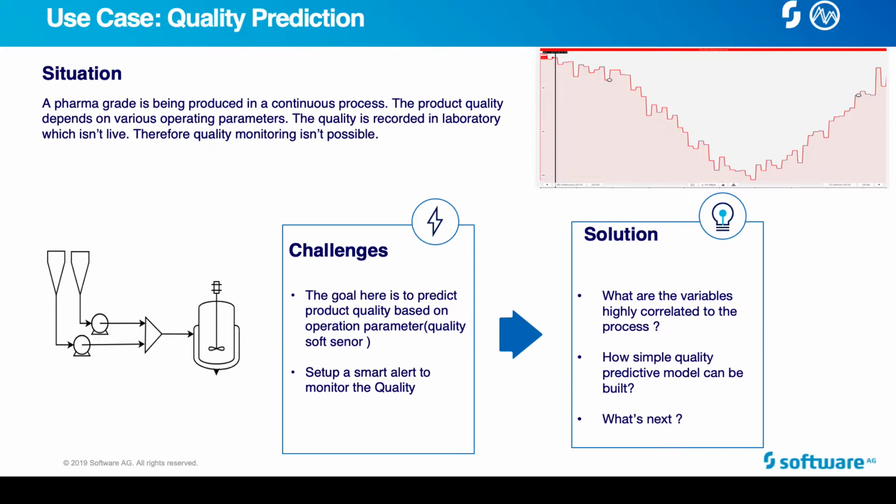Statistically speaking, data is grouped into two main categories: numerical and categorical. Quality data mostly falls into the realm of categorical data of two levels: on spec data and off spec data. Even numerical quality data such as viscosity, molecular weight, or assay can still be broken down into categories of on spec or off spec data. However, plant data, on the other hand, is generally numerical in the sense that field sensors such as pressure, temperatures, and flows are generating time series data on a continuous scale within a given range.